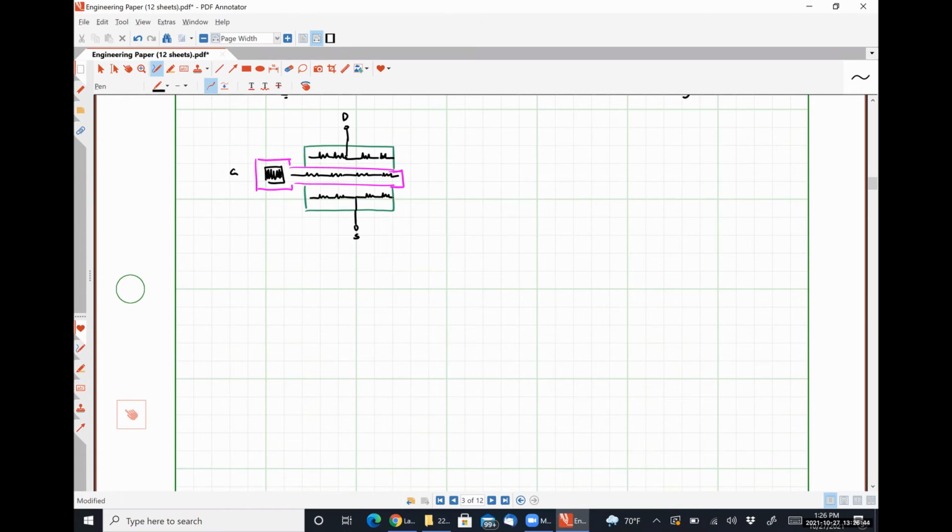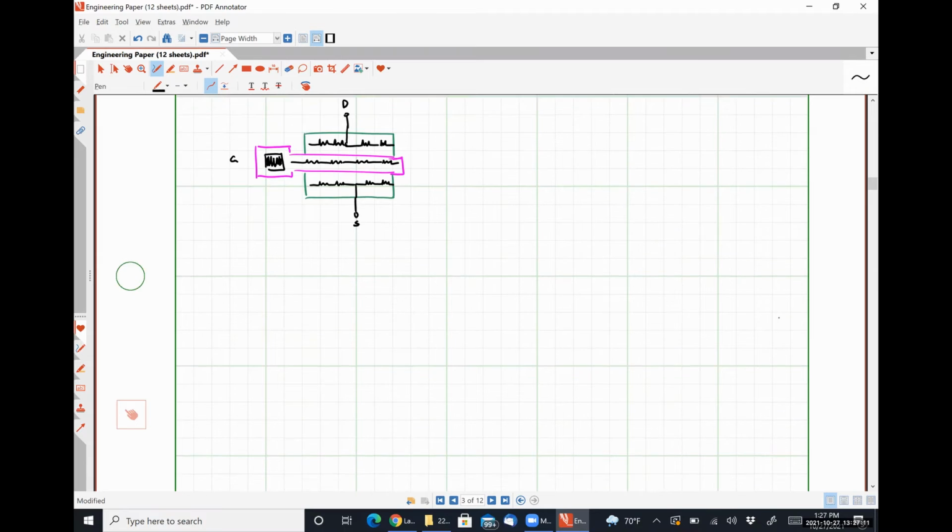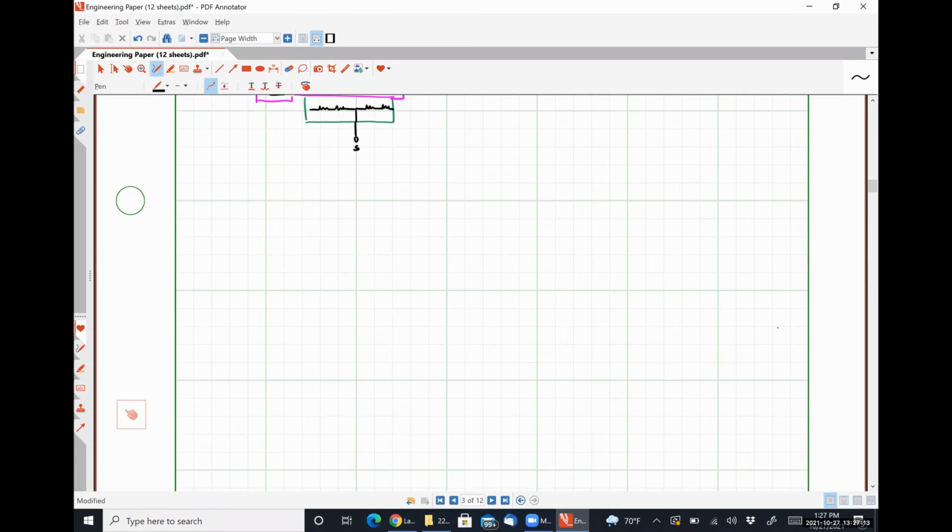The polysilicon gate resistance, however, can be problematic, okay? So if we had a very wide transistor, that means we have a long section of polysilicon, and the longer that section is, the more resistance our gate has, and that can contribute noise to our system. So to analyze what those effects are, we are going to use a distributed model to see what's going on here, right?